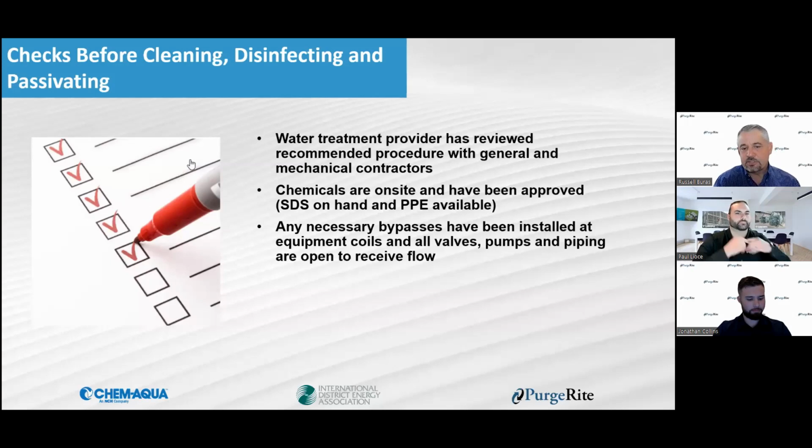And then, as I've already stated, that you really have the system prepared to flush correctly. And again, that could require some extra bypasses, some valves, some procedure things you need to do to zone off the system. And again, those are not typically seen in your base design for building or constructing a new chilled water system.